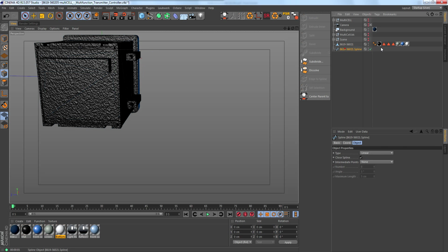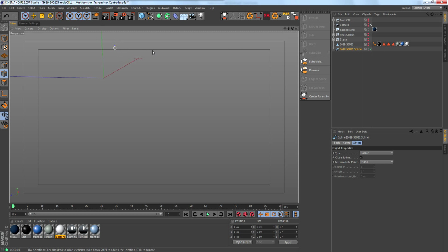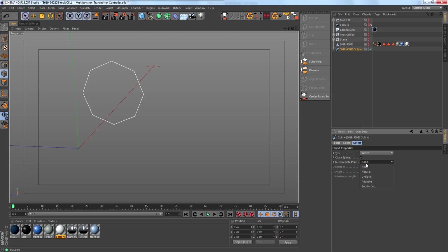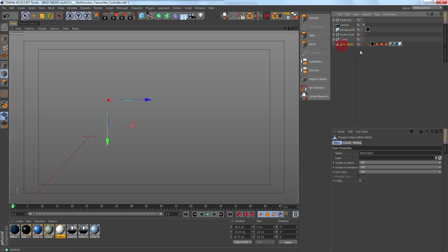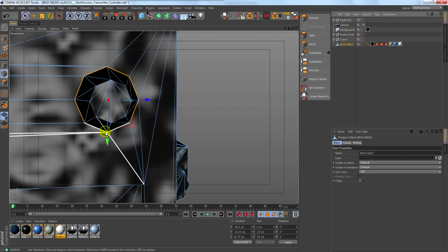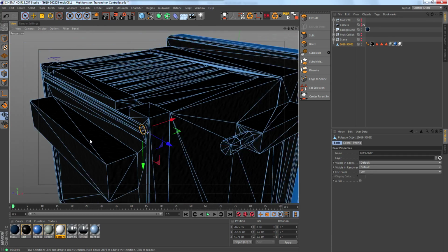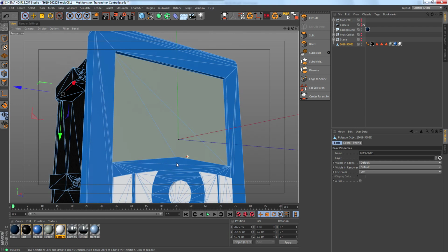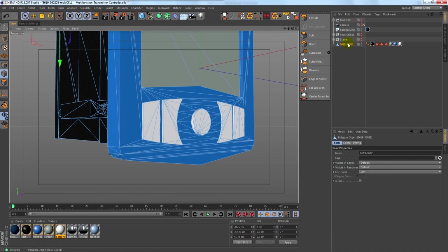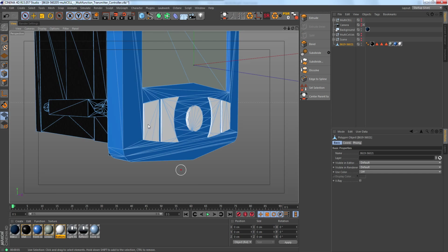Now if we do the same thing again, bring this out, hide that, zoom into this, change the points real quick, Bezier, natural. Now we are nice and smooth. Okay, so that's why you have to do it individually. Depending on the file you've got, you may be able to select multiple ones and convert them to a spline, and you may get away with it. But for this particular example, that didn't work.